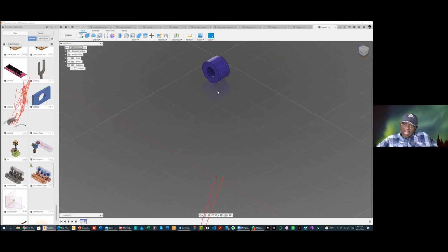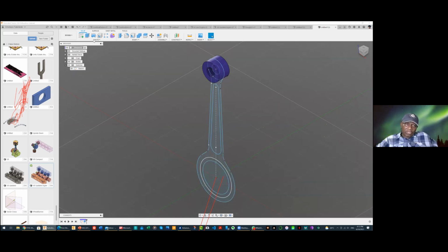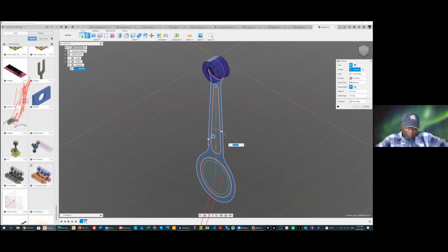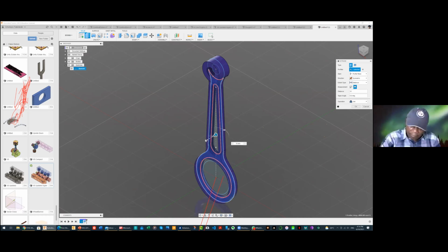I can create another extrusion. Create extrude. Okay, I can even use the marking menu. Okay, no, it didn't give me that. So let us create another extrude. And then I want it to be symmetrical. And I want it to go, let us say, the double length of 10. Or 15. So this is 15, and I want it to be a new body.